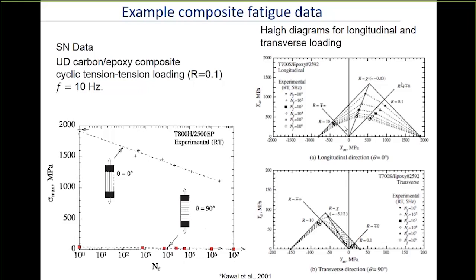So this is what the top plot is for loading in the fibre direction, and you see that it's giving us good static and fatigue strength in tension, rather weaker, as I mentioned, in compression because of a different mechanism. One of fibre buckling is having an influence here. However, if you go in the transverse direction, we find the reverse is true.